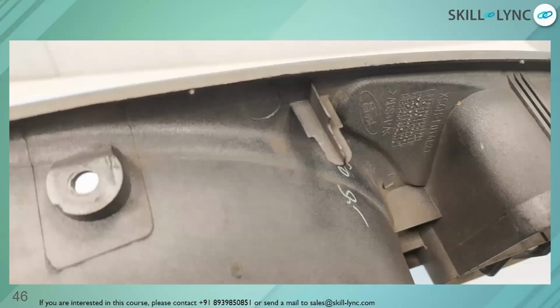Okay, so when you look into the locating parameter, we try to look into some of the GD&T parameters also, the geometric dimensioning and tolerancing. So what that is basically with respect to arresting the degrees of freedom with respect to motion of the plastic components. Okay, so it's used for locating, as the name suggests, locator.